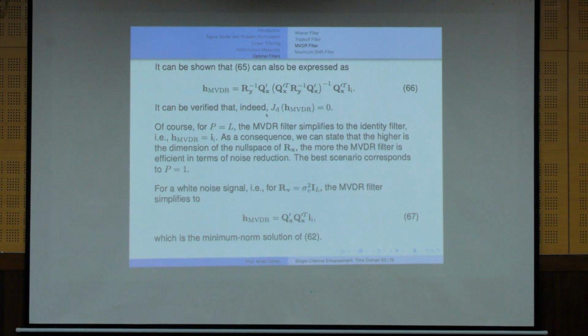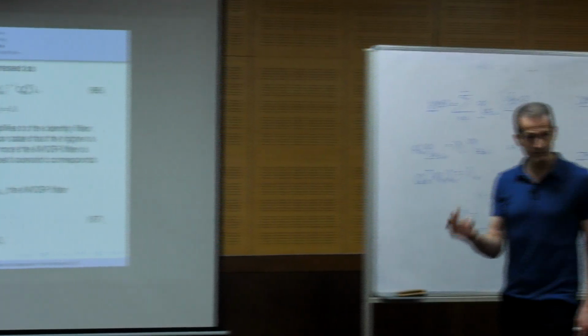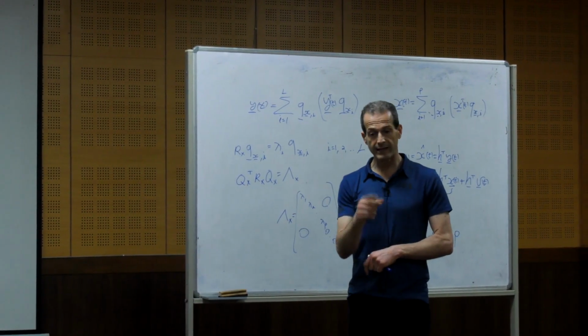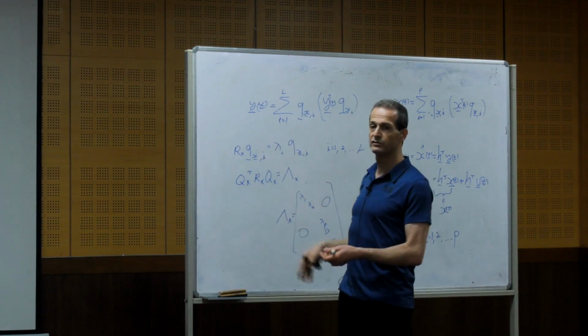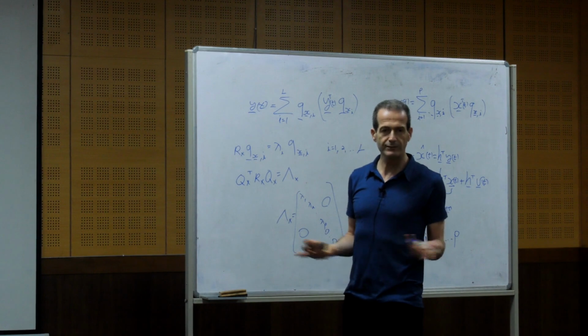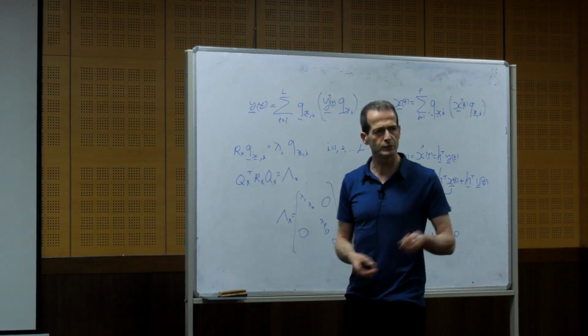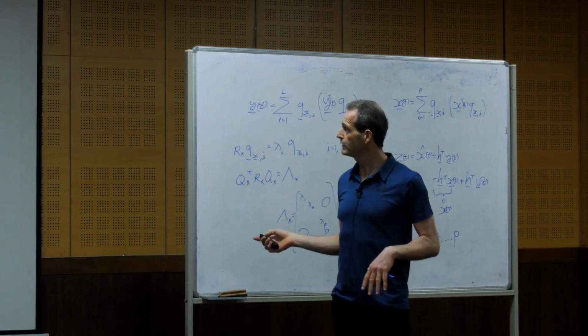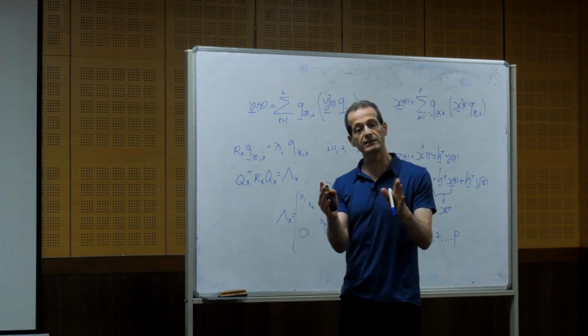Think about it. Suppose that I have a non-stationary signal like speech. For each interval of a few tens of milliseconds, I need to find Rx, and then I need to find the matrix Q, the eigenvectors that diagonalize Rx in that window, and then I need to represent the signal and then remove the null subspace and so on, which is difficult. It's time-consuming, high computational complexity, and so on. Instead of that, what do you think if I just use the Fourier transform on that interval, on that window?